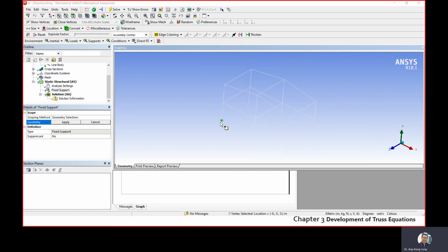So if you do it one by one, you can generate a reaction force in each point here, right? So if you need to determine reaction force later on for each point, then I recommend you to only select one and then repeat it for like 6 times. Yeah, maybe in this case I do 6.